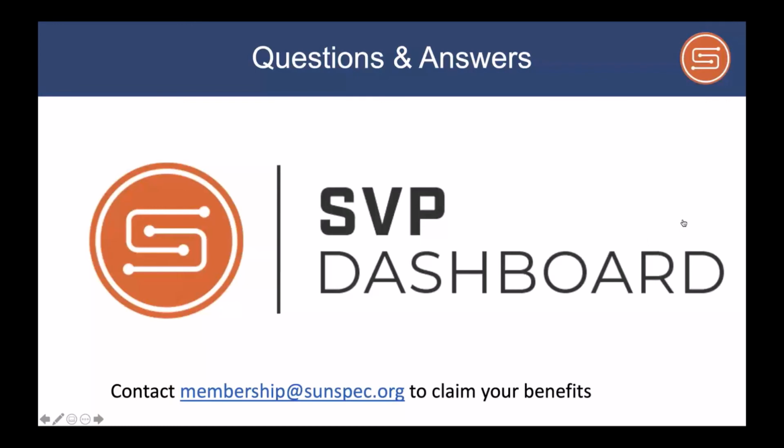Okay, the next question is, is SunSpec tightly coupled with Modbus? Would I be able to certify a SunSpec over maybe CAN? So yeah, this is a great question, and actually represents specific work we've done in our revision. The SunSpec device information model specification, which talks about SunSpec modeling, as Tom said, was rewritten, and we went to a lot of trouble to emphasize the fact that the information models can be used in contexts other than Modbus. So obviously Modbus has registers that have addresses, and there's a sequence associated with the information in Modbus, and that is supported in the information models.